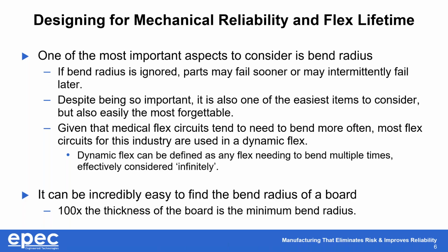And so from my experience so far, circuits in the medical industry tend to be dynamic flex. They tend to be ones that will bend for the entirety of the lifetime. Dynamic flex being anything, like I said, that will bend over the lifetime, a lifetime being considered infinite. A good example would be a ribbon cable for your printer or something of that nature, where you expect it to move back and forth over the entirety of its lifetime.